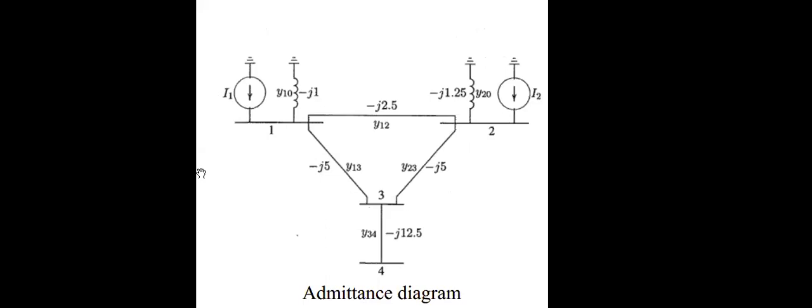Sir, my current direction is opposite, but other than that, everything is fine, sir. Okay, fine. It was node 1, right? So at node 1, if you have current direction upward, it means current is flowing from positive to ground. But what is the regular scenario? It should be from negative to positive for the current source. If you have positive voltage to current source conversion, which direction do you assign? Yes, sir, I've got the point.